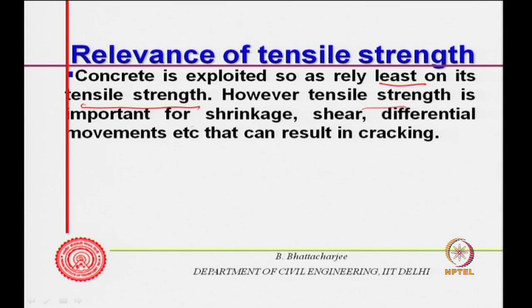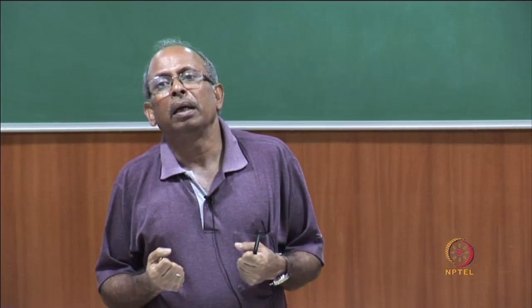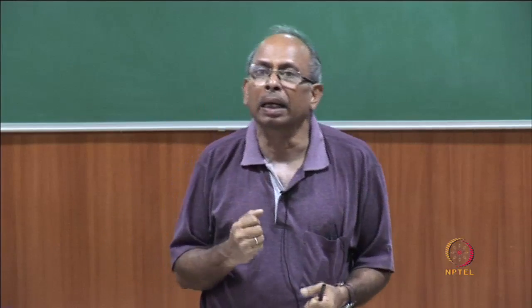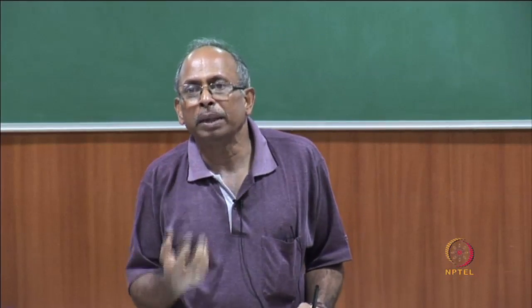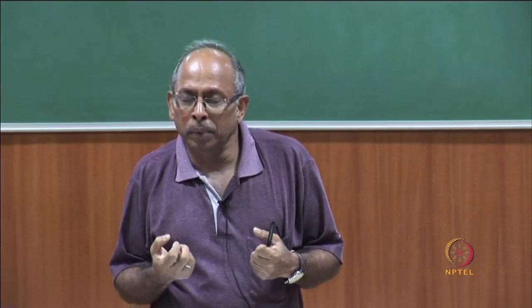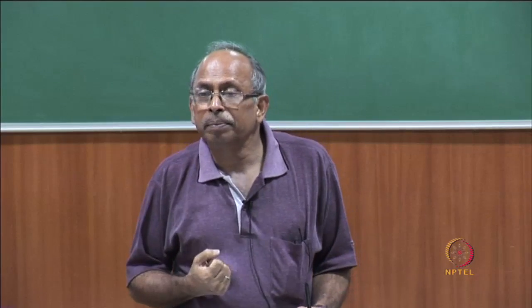However, tensile strength is important for shrinkage, shear, differential movement, etc., because they can result in cracking. Unless you have the right kind of tensile strength, it can result in cracking, because if you have restrained shrinkage, if something is trying to shorten and you are not allowing it, which can happen in structures, there will be tensile forces coming in. You may not expect direct tensile load to be resisted by the concrete, but tensile stress comes because of the shrinkage.